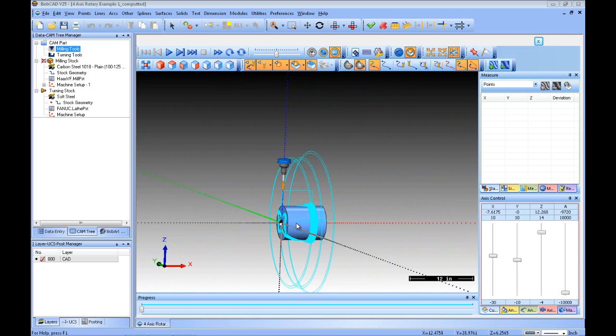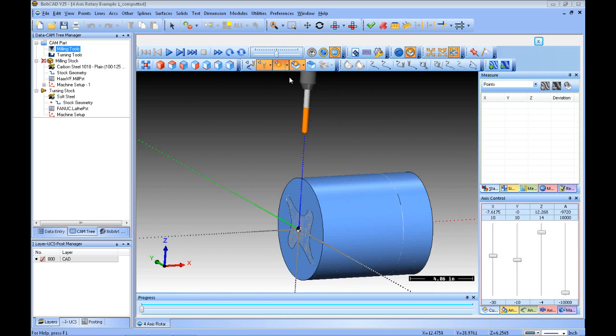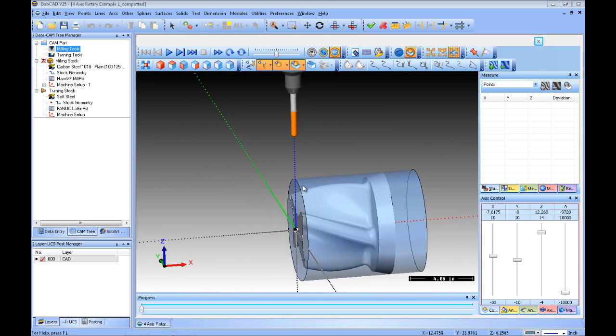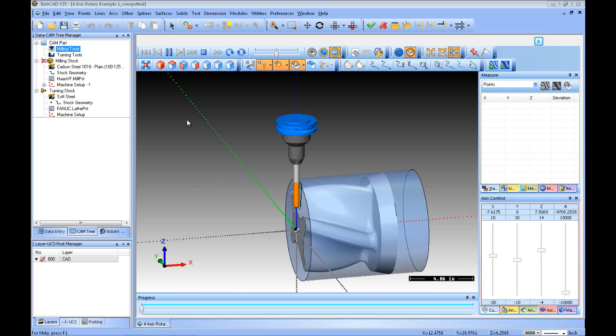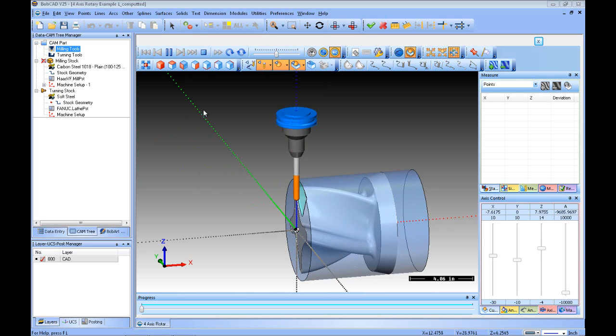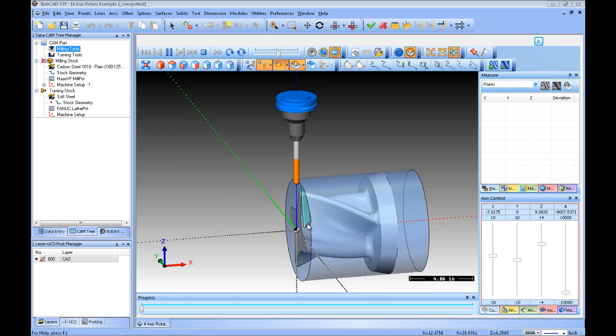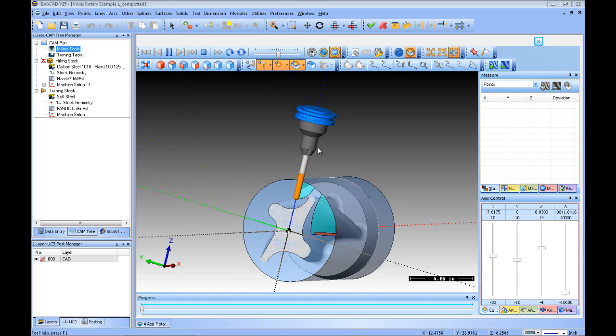Here's my travels, and you can see what these are out here: when it hits its maximum rotation, it has to lift up, rewind the rotation, not the spindle, but the rotary axis, and come back down and continue on. So you can see if I turn off the tool path and the initial workpiece. Actually, let's turn back on the workpiece since we haven't made our stock transparent so you can see it in there and hit play. You'll see it's actually moving correctly as it's rotating around. So you can see how that's cutting out there.